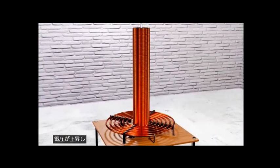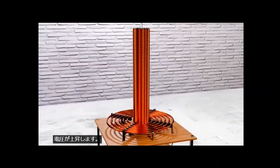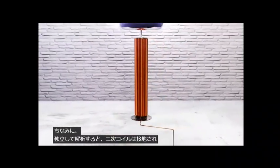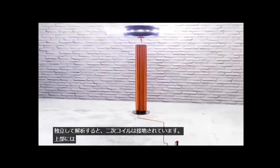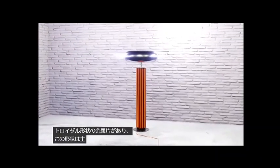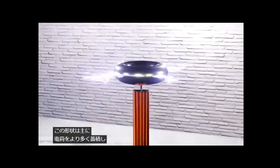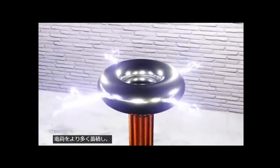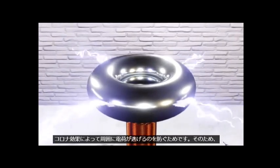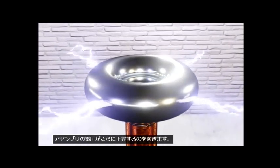This will increase the voltage in the secondary coil, which, by the way, if we analyze independently, is connected to ground, and in its upper part it has a metallic piece of toroidal shape. It has this shape mainly to be able to accumulate a greater charge and prevent it from ending up escaping into the environment by the corona effect, and therefore also preventing the voltage of the assembly from increasing further.